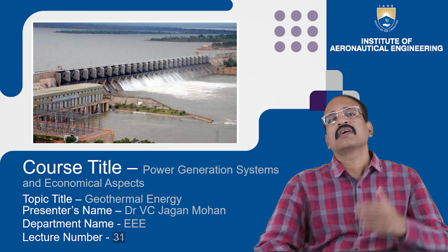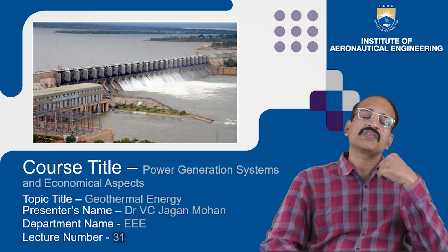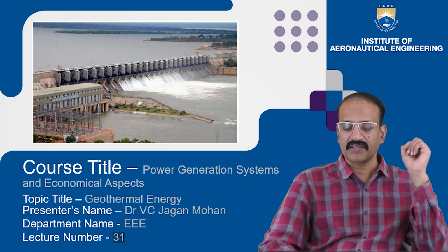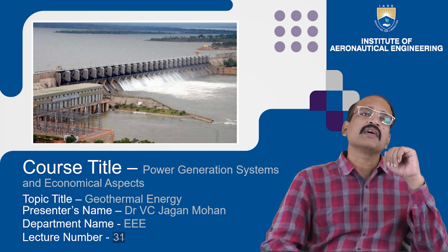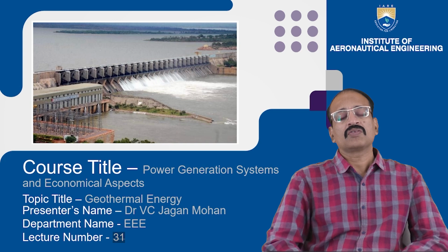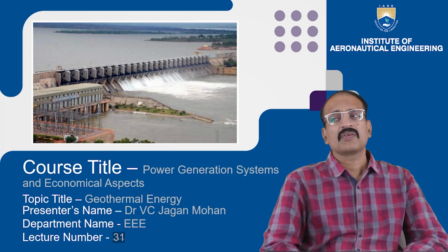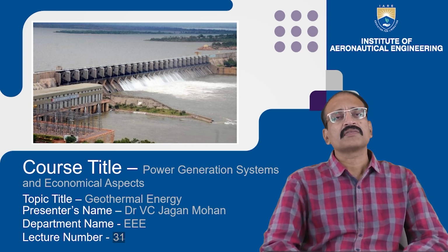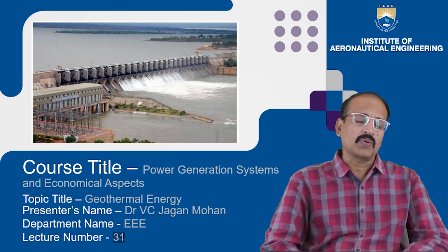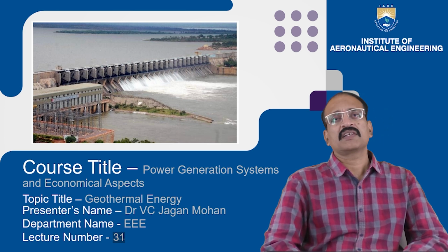It requires two reservoirs. Normally a dam means one reservoir is enough, but this requires two reservoirs. Otherwise we cannot satisfy the purpose of meeting the peak load, because it is a pumped storage dam.